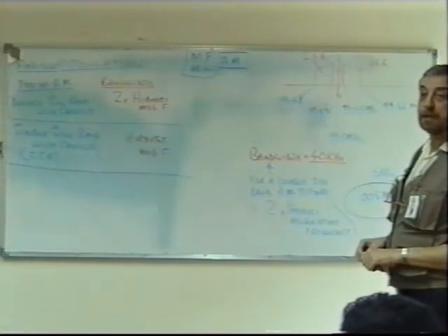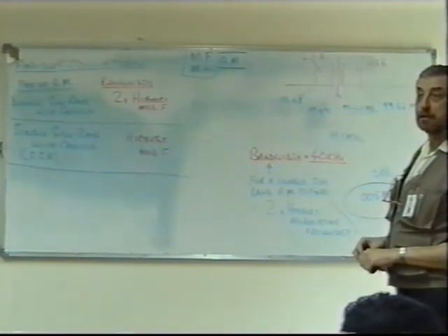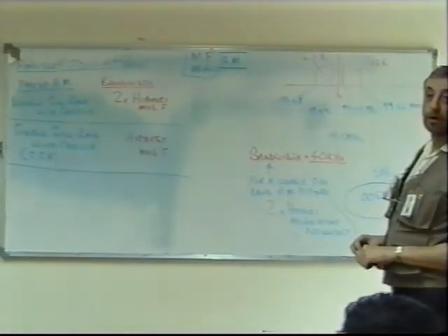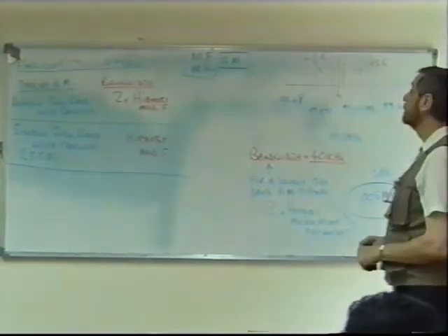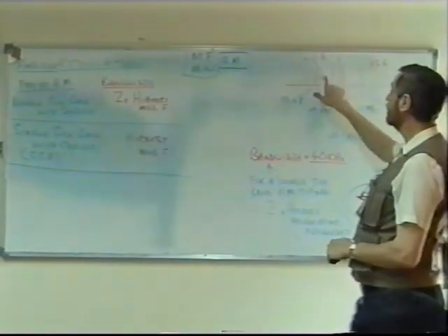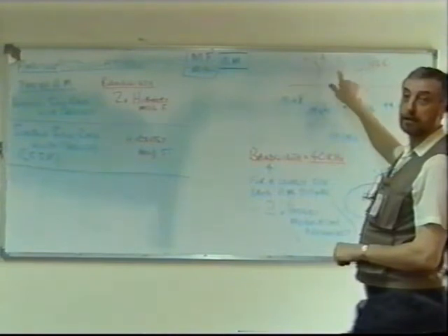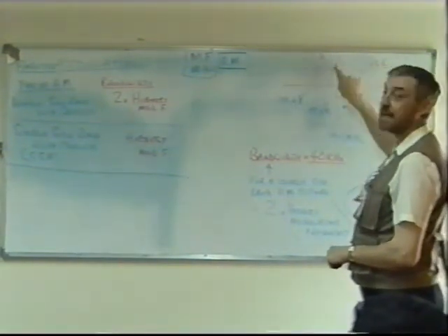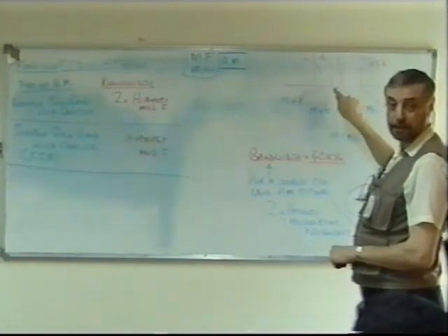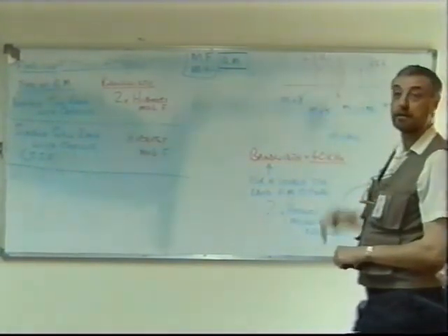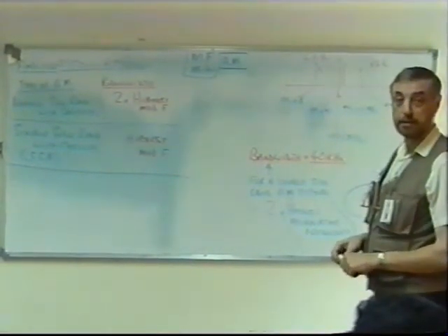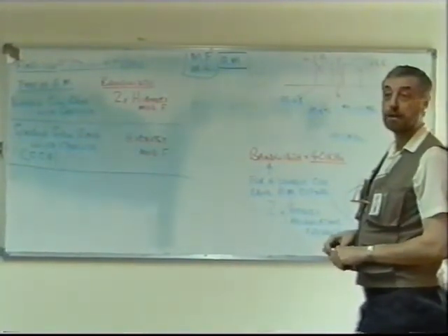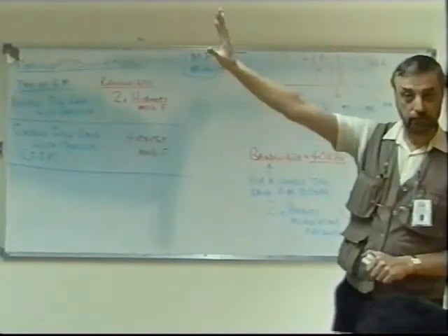Can you transmit SSB? Yes. You have to isolate that. One very simple solution to this is first of all generate in your transmitter this, and then use a filter to select one band, either your upper or your lower sideband. That's the way it's normally done. And then just transmit that one band of frequencies.